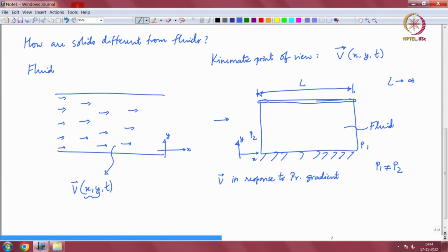That is one way of course, and the other way you have probably seen, a Couette flow solution, plane Couette flow, is you take one of the walls, let us say the top wall in this case, and you apply a velocity to it, okay. I will just call this V0 bar to distinguish it from the bulk velocity, okay. So, if you do this, then you can also get the fluid to flow in response to a boundary velocity.